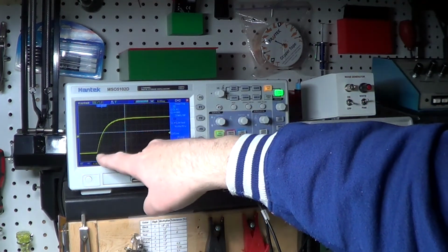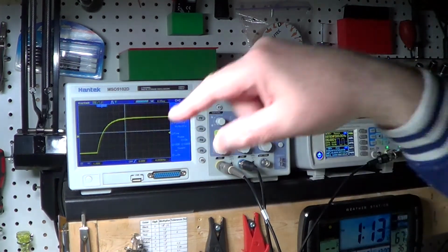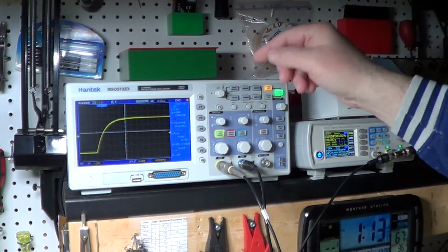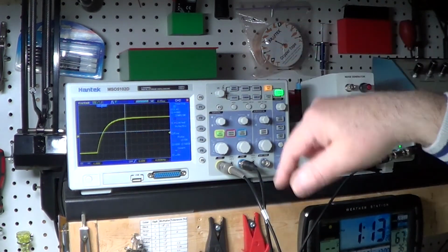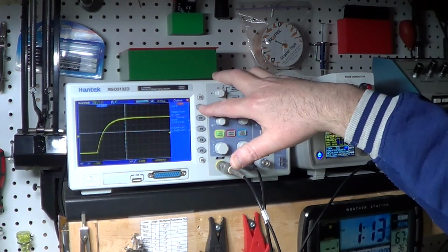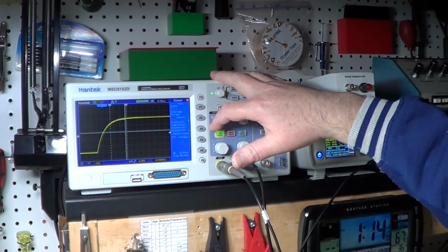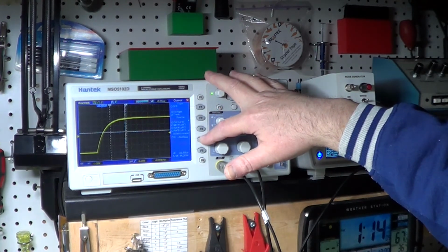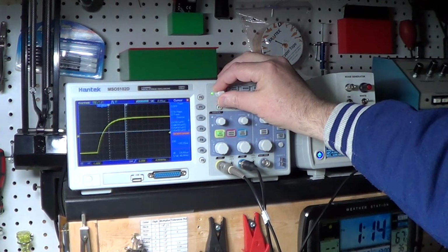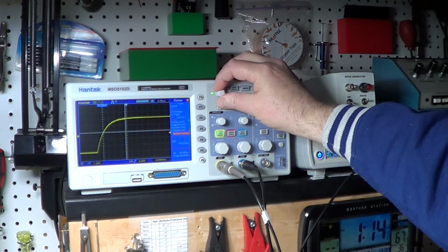So we need to measure from 10% of this, so from 0.5 volts to 90% of it, which is 4.5 volts. So let's get the cursors again and let's do this kind of measurement. This time we are gonna use measure frequency, and the source is gonna be channel 1, of course. There we go. So let's start with the start cursor, of course, and so let's position it in the place where the signal has 0.5 volts.